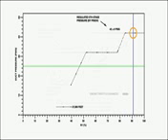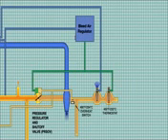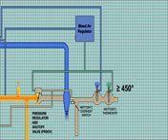Low pressure in this example could be caused by a problem with a PRSOV or bar, so troubleshooting efforts should concentrate on these components. But remember, if the cooling system is not sufficiently cooling the bleed air, the 450 sensor will cause the PRSOV to reduce duct pressure to increase cooling. So you should also troubleshoot the cooling system, including the PCCV, the 390 sensor, and the 450 sensor.